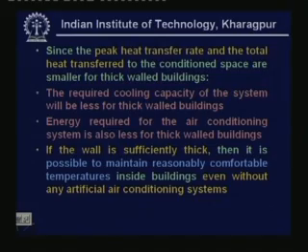In fact, this is the principle behind the old temples and old forts or old buildings which have very thick walls. You find that these buildings even without any air conditioning are very comfortable even during peak summer. This is because of the large thermal capacity of the building, which introduces small decrement factor and a large time lag.